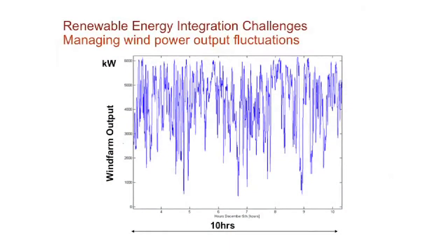This is what you actually see out of the wind plant. Now this is actually typical out of every wind generator. We discovered nearly 8 to 10 years ago that you can lose up to 80% of the output of a wind turbine and have it come back in under 3 seconds. So any wind turbine put out in the wind farm will actually lose and regain its rated power or its output power over that sort of time base, over a few seconds.